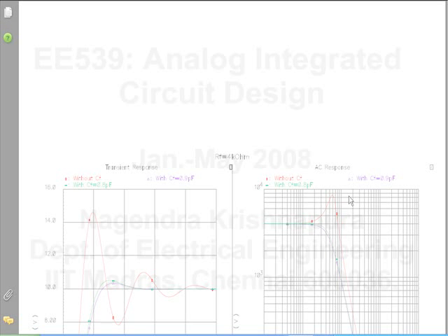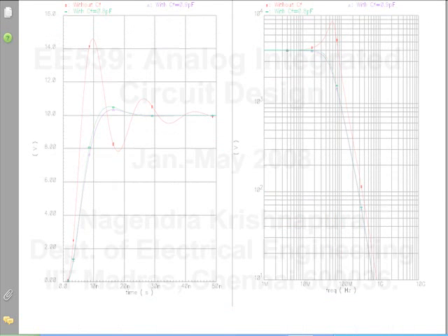Okay. So the red curve here on the left side is the time domain response and the right side is the frequency domain response. Shows quite a bit of peaking and also ringing. So it takes a long time to settle also. So if you put in a square wave, you will have to wait until here so that each time the square wave is settled and then it comes back. Okay. So one of...